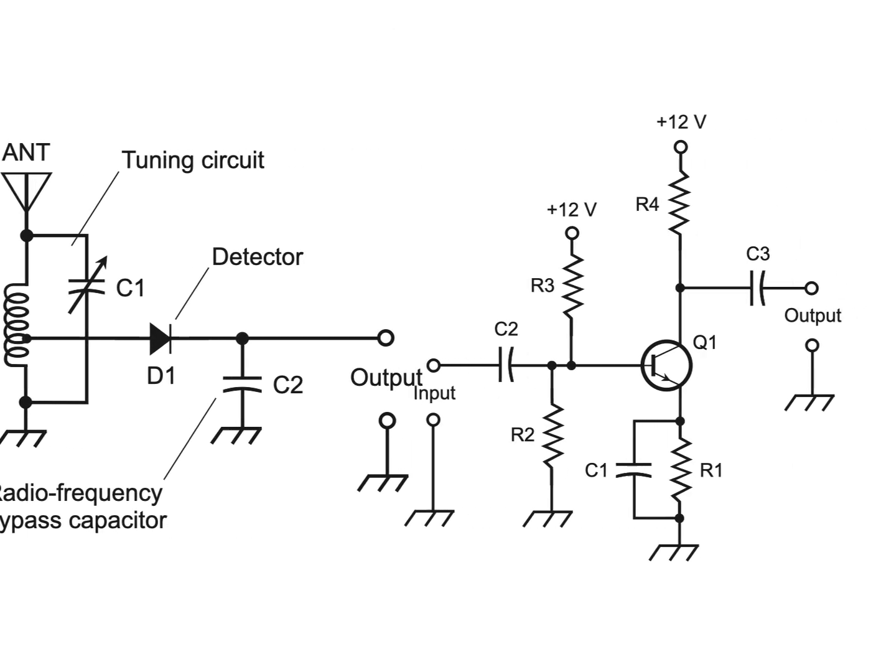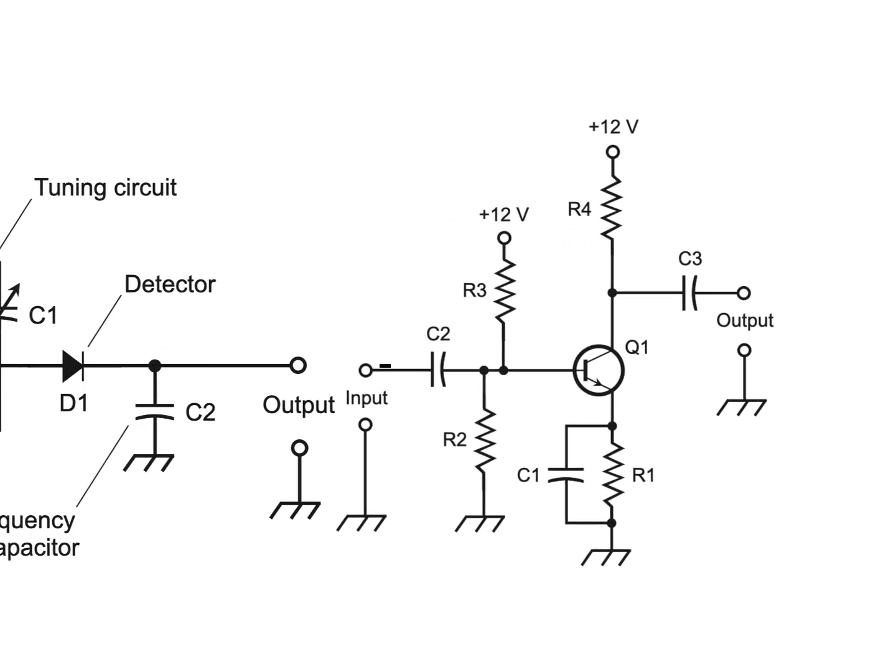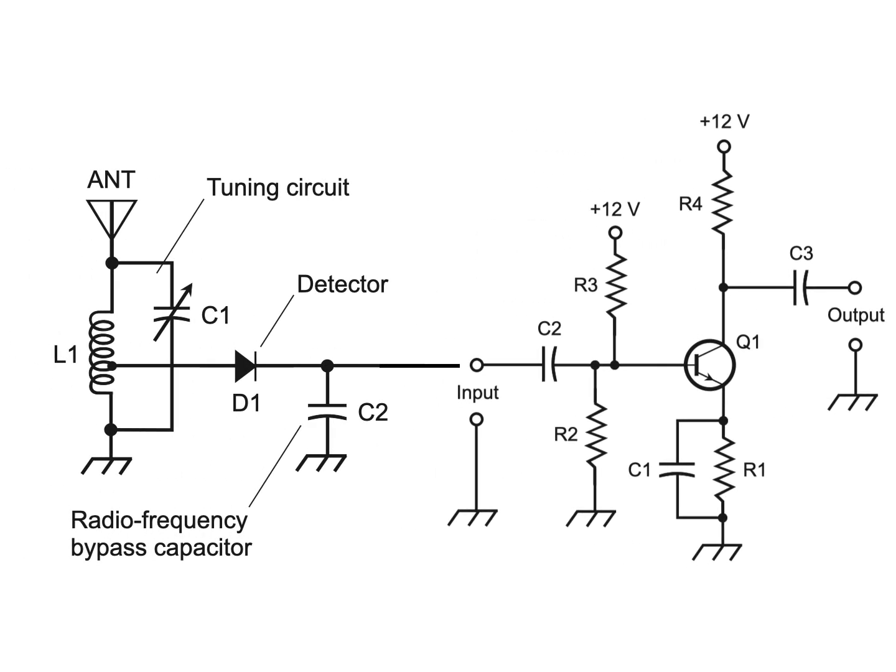This shows another fairly simple schematic diagram, an audio amplifier that makes use of a single NPN bipolar transistor. In addition, this circuit has 4 resistors and 3 capacitors for a total of 8 components. It also needs a source of DC power, such as a battery, which provides 12 volts. This circuit can accept low-level audio signals, for example, the output of a crystal radio, at the input terminals and boost the power to a level strong enough to make a nice loud sound come out of a headset.